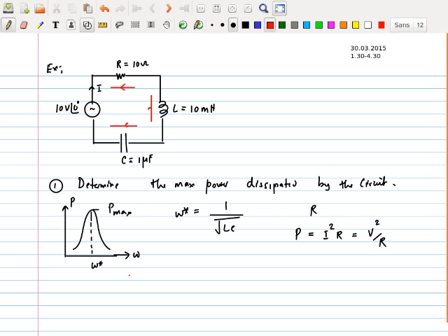This is very hard to understand, right? Now, in all the other circuits we say that if there was an element, there was some voltage across it. Here, this is I, that is VR, this is VL, that is VC, and VL is equal to VC and opposite in direction. So when you add up the voltage for the reactive part, it is 0.